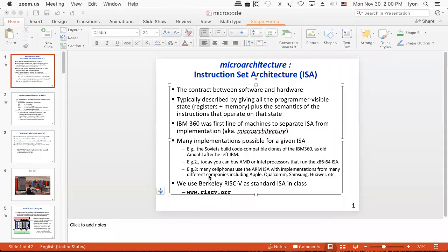What I do is wrap up a topic that I'd been putting off for a little while. This is the topic of microcode. When you try to create a new CPU, oftentimes you get involved with creating new instructions, and each one of the instructions has to be able to go through a generalized process, which we've discussed before. This process involves decoding an instruction after a fetch, executing the instruction, storing the results, and then going to get the next instruction.